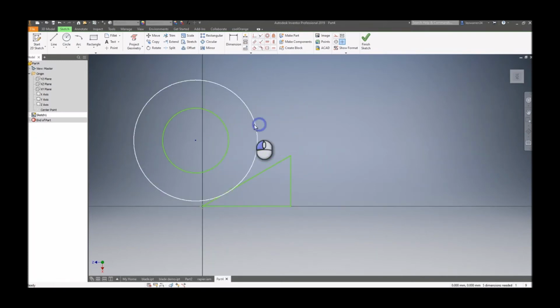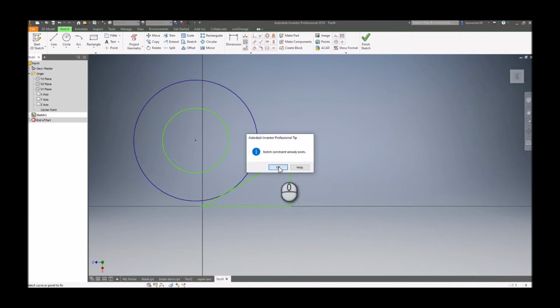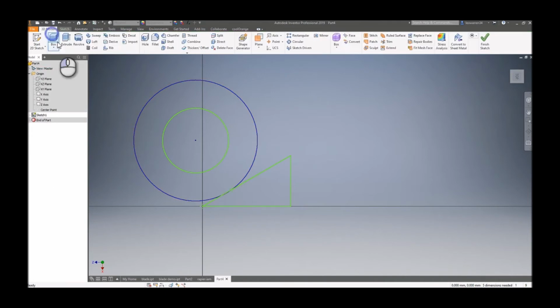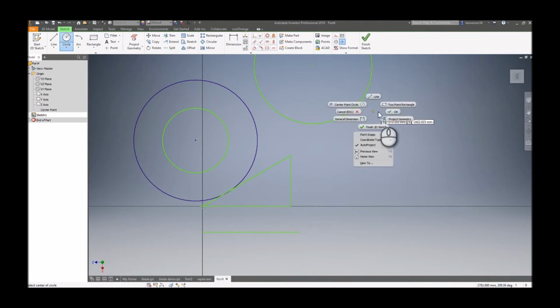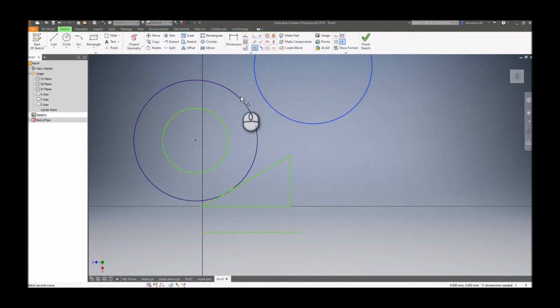Okay, we get your point. Click OK. So then you've got parallel constraints. So if you just go back to sketch, I just want to make these two parallel. There you go, parallel now, fixed. These are called parallel to X and Y, so these relate more to your axes. This has got a tangent one, which is the same. So if I now just do another circle, tangent, tangent, then we're tangent.